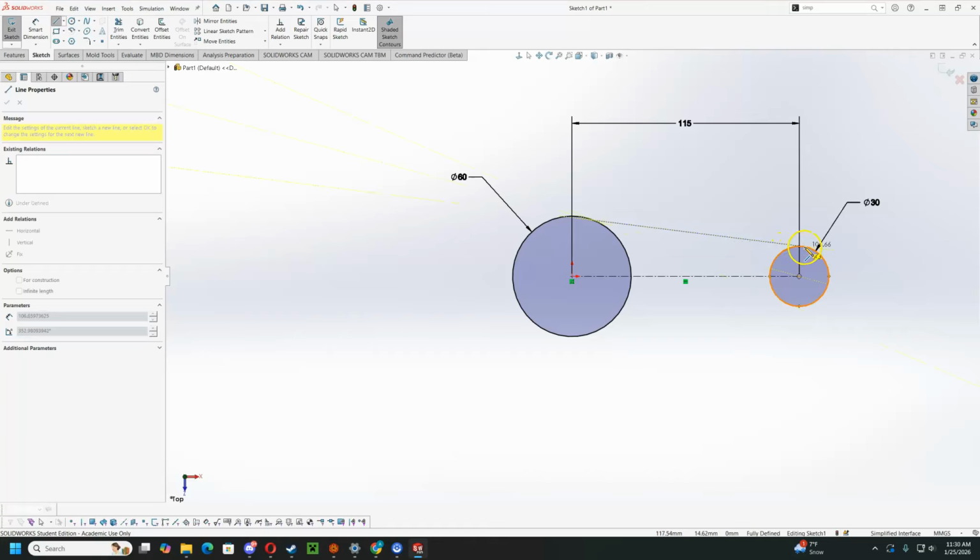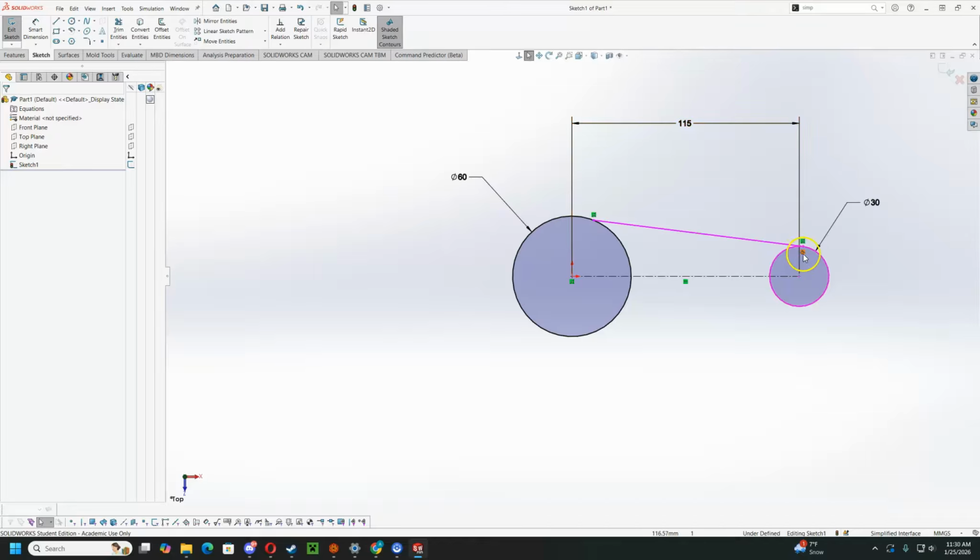Now, the biggest mistake that people make here is just pinning it right to the top of the circle. But the tangent point is not actually at the top of the circle, it is beyond. I'm going to keep sliding, and you see right there, it's a little hard to see, but next to my cursor, I get the relation symbol for tangent. And if done right, I should end up with 2 tangents, although I didn't end up with one here.